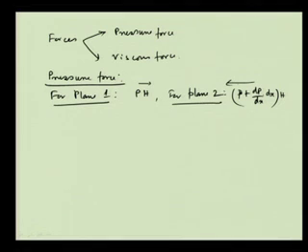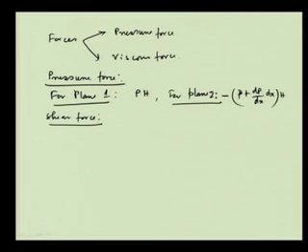And there is another part, that is the shear force. So the pressure force at plane 1 is P H, and at plane 2 it is minus of that. The shear force at the wall is minus tau_w into dx, with 1 as the area.